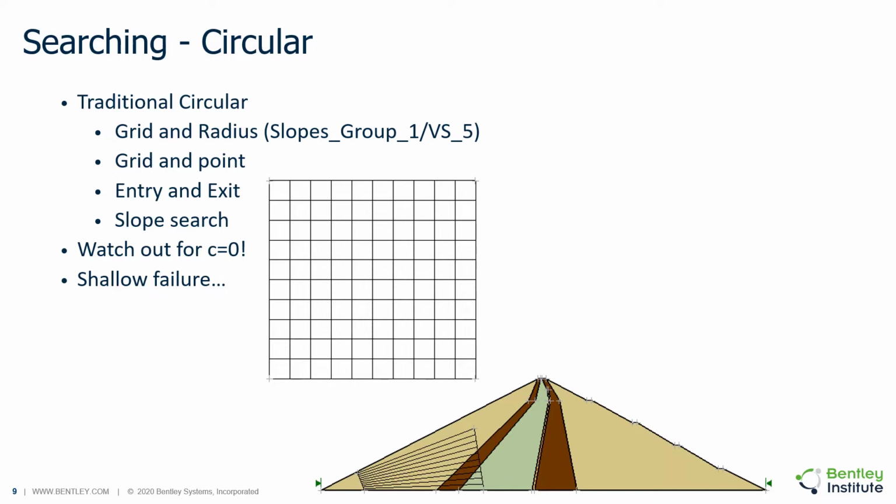Also, if materials have no cohesion, the slip surface will tend to rise to the ground surface and shallow failures will be preferential. Some cohesion is often required to be entered to realistically represent slip surfaces that are not shallow. Unsaturated sections also act like cohesion and tend to remove the risk of shallow slip surfaces.